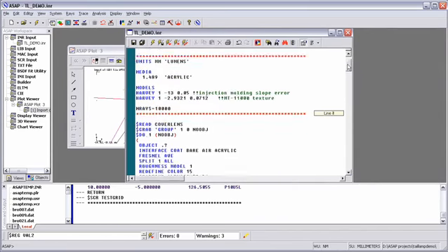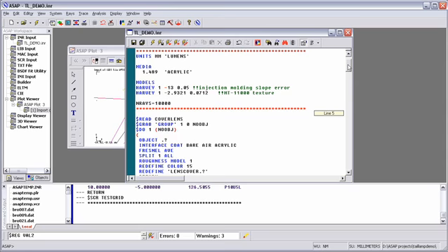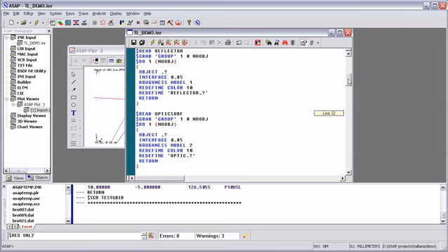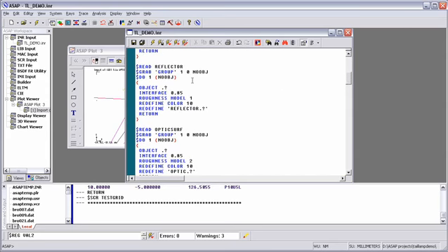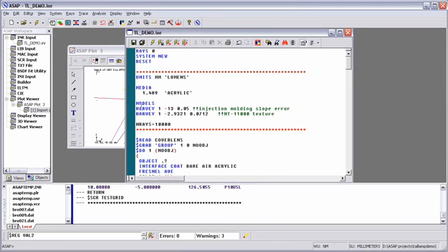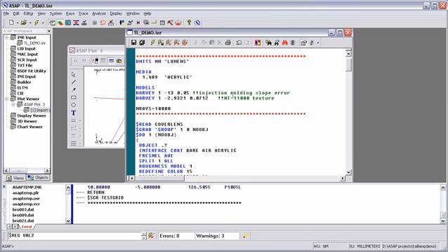I mentioned up front that I didn't do the material assignment to the geometry with the IGES translator, to allow me to change the parameters of the design quicker. One of the things I've set up in this particular file is roughness models that simulate different surface finishes, one of them being a simple model for simulating injection molded parts, because they're not going to be perfect, so it simulates a modest amount of slope error.